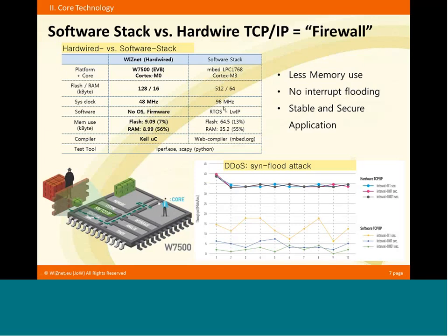Even this is running with nearly 100 megahertz, and in the application used a small operating system with a very sophisticated embedded IP stack. We occupy already 64K of flash and 35K of RAM. So it's quite occupied, and performance is like zero.